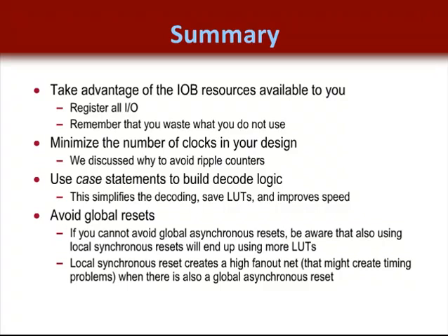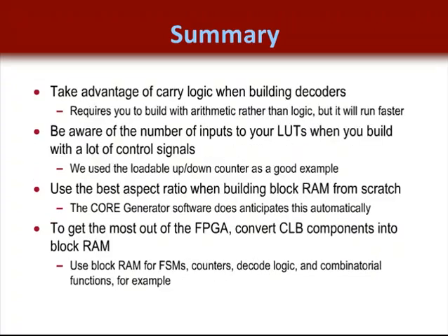Use case statements to build decode logic. This simplifies the decoding and saves LUTs and improves speed. Avoid global resets, and we've talked about that a couple of times. Take advantage of carry logic when building decoders. This requires you to build the arithmetic rather than a logic implementation, and it will run faster.